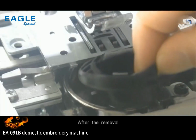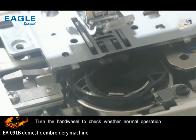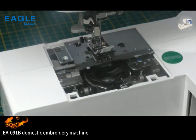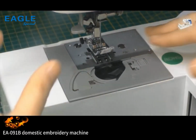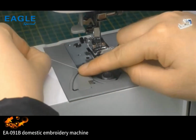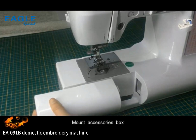After the cleaning, load the hook normally into the bobbin case. Turn the hand wheel to check whether it operates normally. Cover the needle plate arm. Add the bobbin. Put on the transparent bobbin cover. Mount the accessories box.